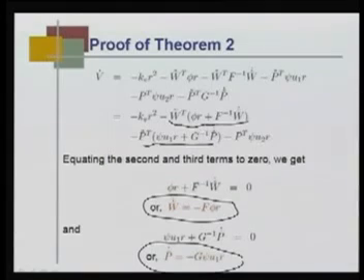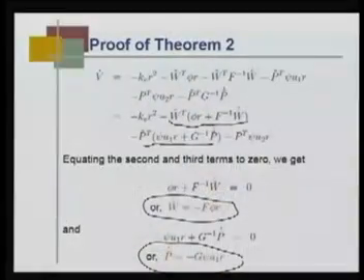If w hat dot is minus F phi r and p hat dot is minus G psi u 1 r, then this is Lyapunov stable, but we have not actually proved it, because even if we do that, V dot is minus k_v r square minus p transpose psi u 2 r. So, there is an extra term here.